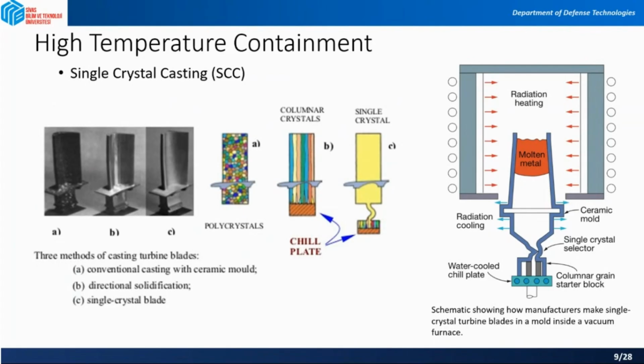This high thermal efficiency is dependent upon high turbine entry temperature, which is limited by the turbine blade and nozzle guide vane materials. Continuous cooling of these components allows their environmental operating temperature to exceed the material's melting point without affecting the blade and vane integrity. The heat conduction from the turbine blades to the turbine disc requires the disc to be cooled and thus prevent thermal fatigue and uncontrolled expansion and contraction rates.